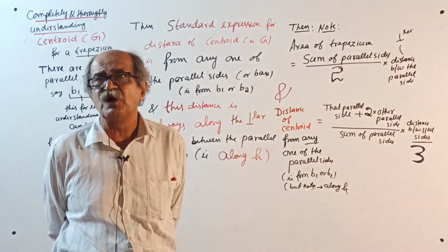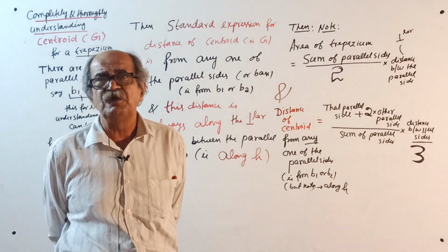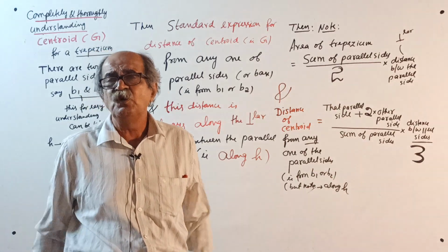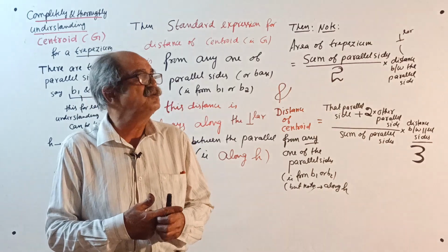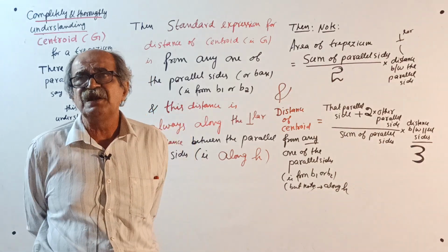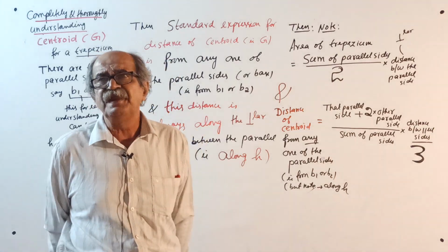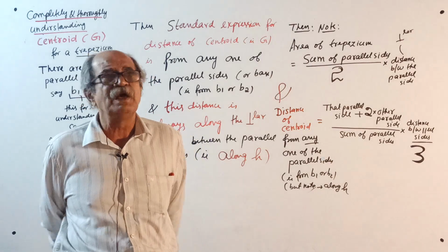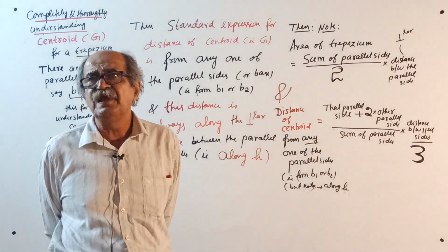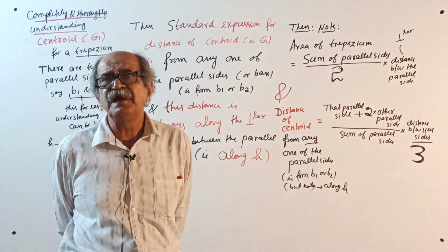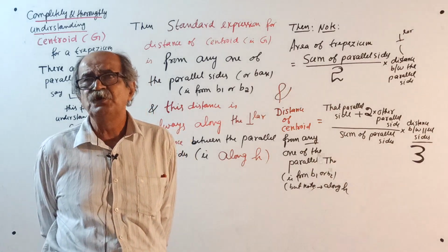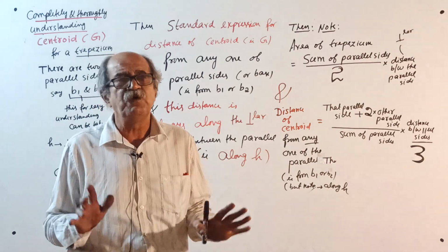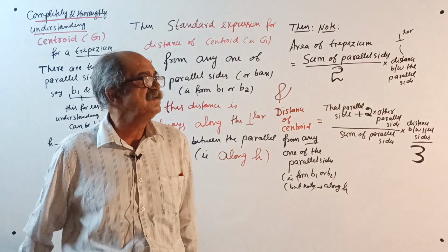Because we consider it trapezoidal, there will be some small curvature that you are not considering. And also, even for examination, or in structural analysis, when you go to the moment area method, conjugate beam method, etc., their bending moment diagram will come. You require area and centroid for that diagram. Many times you get a trapezium there. So, understanding centroid for a trapezium is very important.